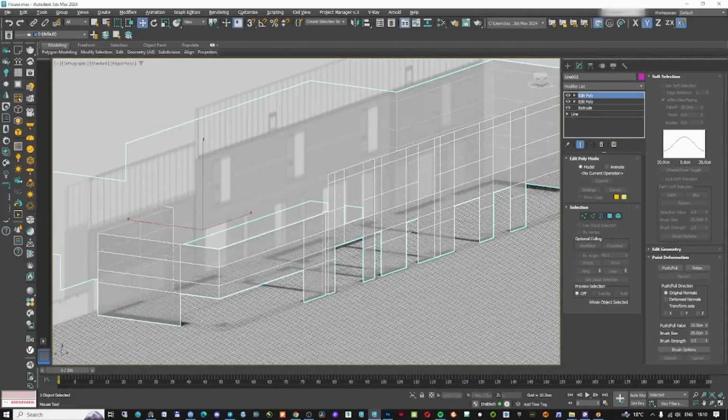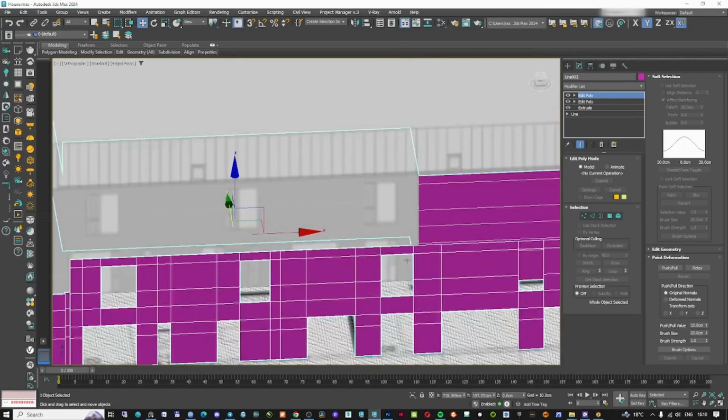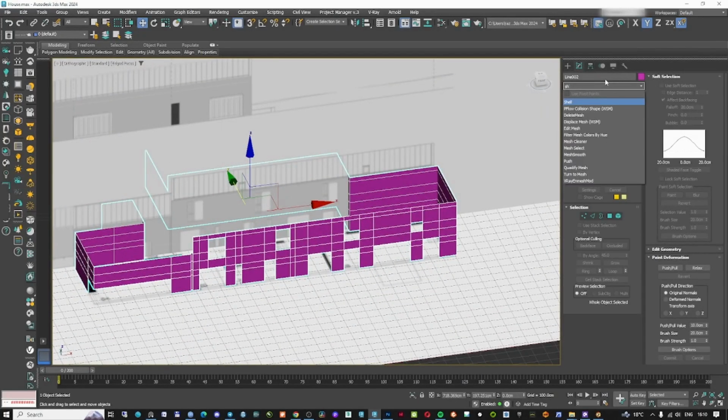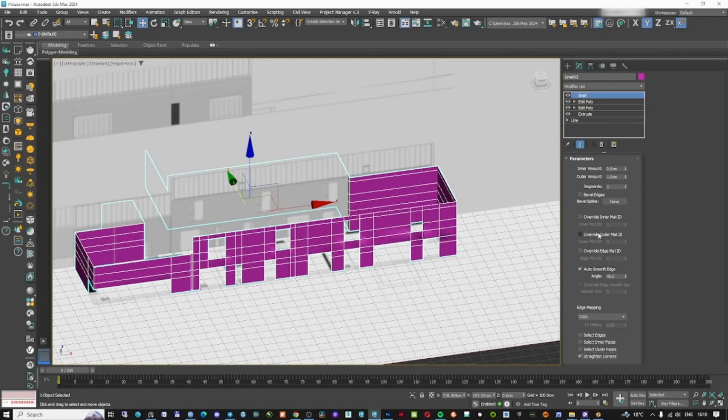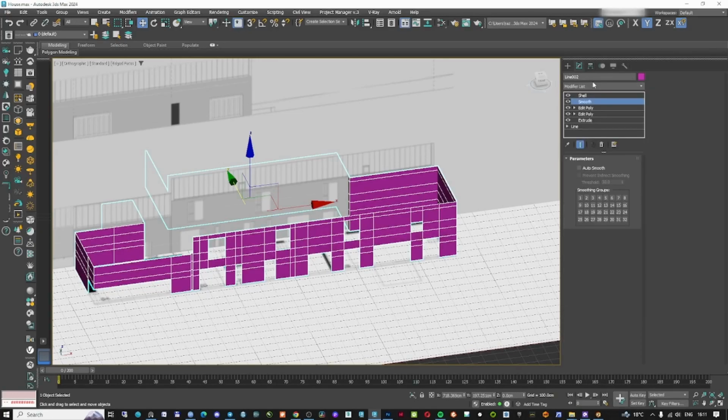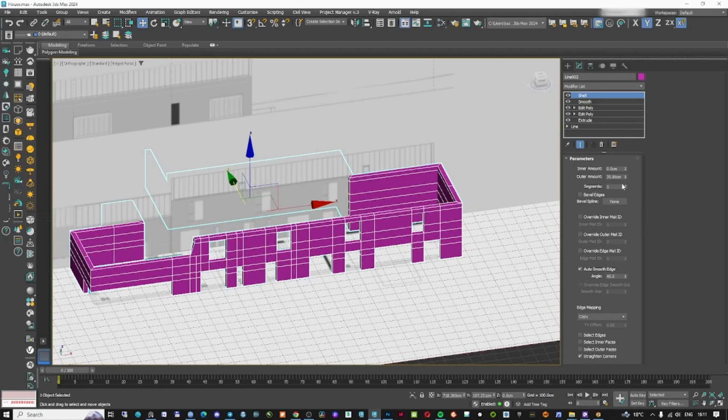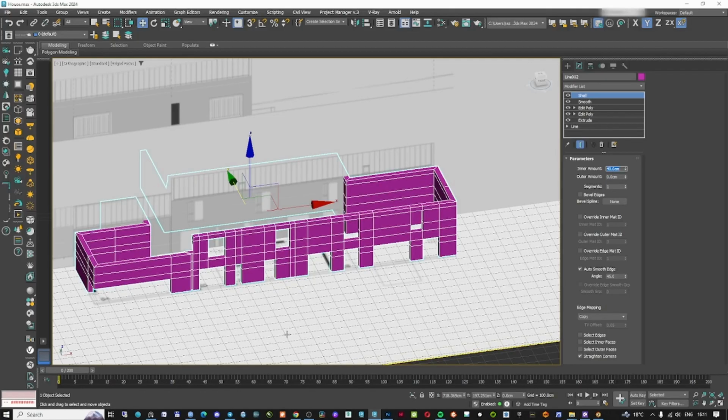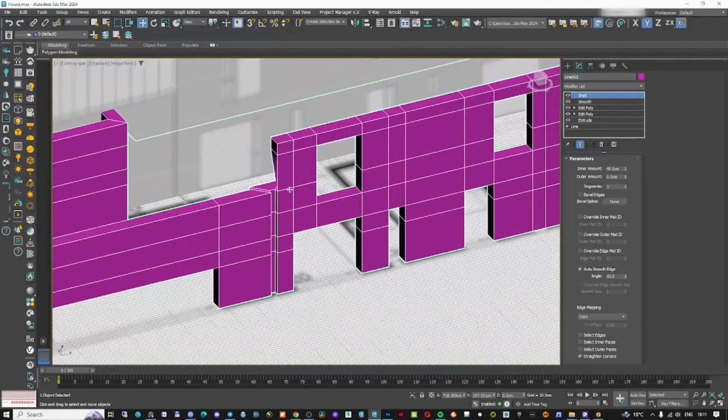So as you can see, this technique is quite simple. You are just using lines and then you extrude them, and then you apply a shell modifier on it and you have the walls. But sometimes you can get really strange corners, as you can see in this part.